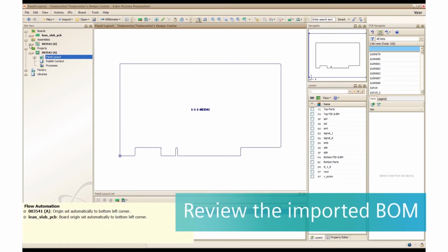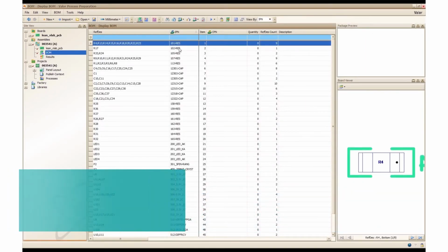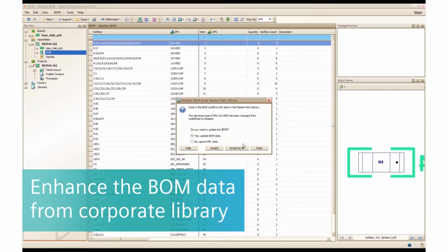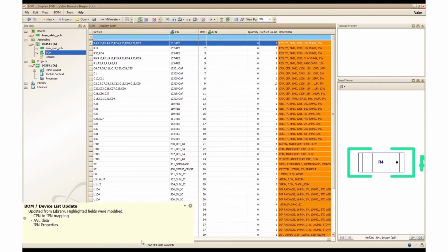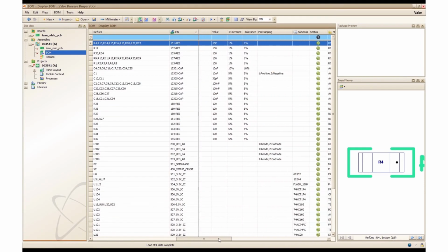Here we see the unloaded PCB, the assembly that contains the BOM, and the project that contains the panel. Let's look in more detail at the BOM using the part number for each component. Additional manufacturing data can be imported to the project that will streamline the creation of the manufacturing collateral. For example, this can be test attributes needed for ICT or SMT machine preferences.